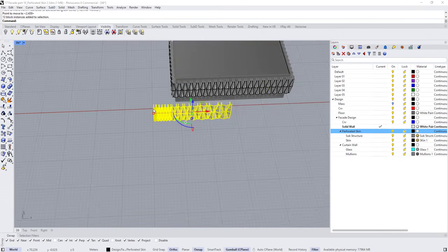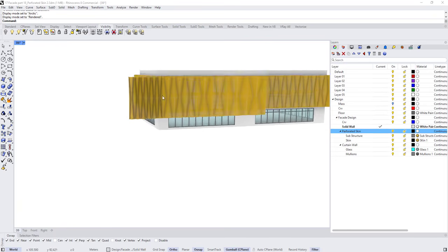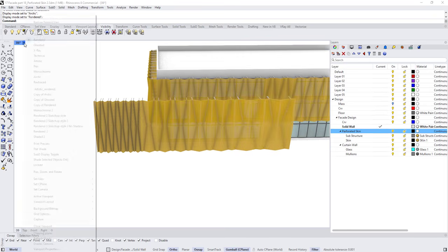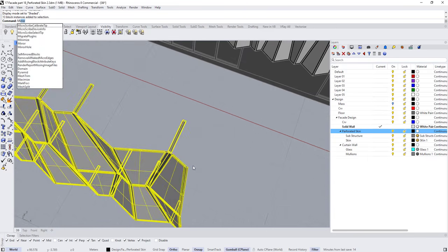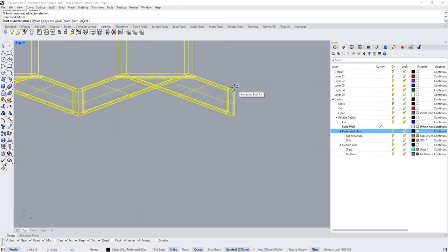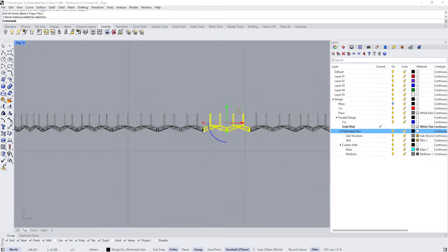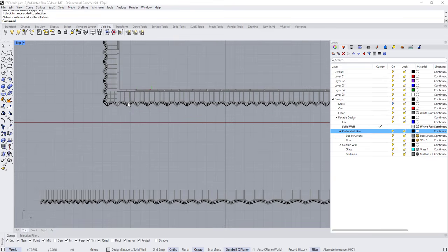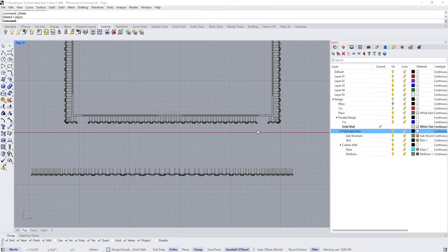I want to see how it will look. It actually looks good. Not bad. Okay, so I think I'm going to also create a mirror. So type mirror, let's go to top view, snap here this point and create a mirror like this. Now we want to fit it here, starting from here. Delete this one, delete all of this.